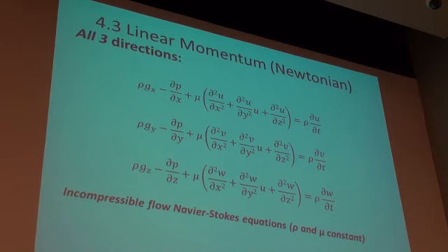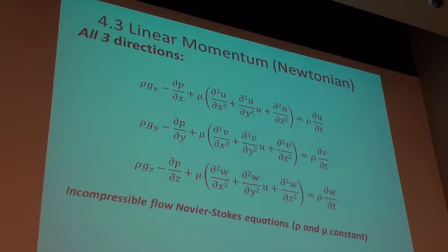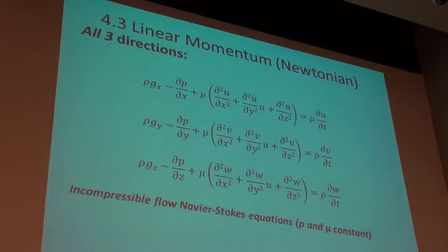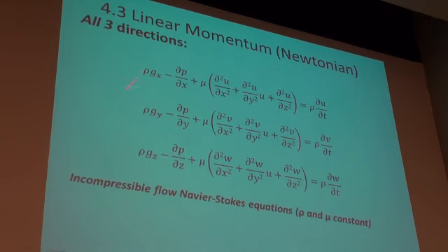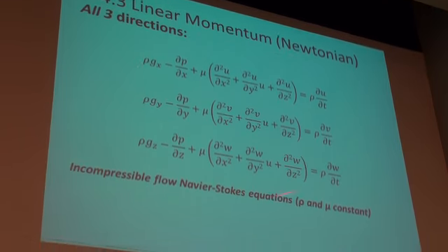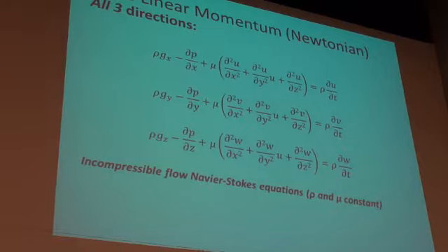They are not always valid because there are fluids which are non-linear. If they are non-linear, the relationship between the stresses and the viscosity is different. Your blood, for example, is such a type of fluid, and then these equations would not be valid. So you have to go back and put that correct relationship in, and then use those equations. But mostly in mechanical engineering, those are the equations that we solve, and those are called the Navier-Stokes equations.